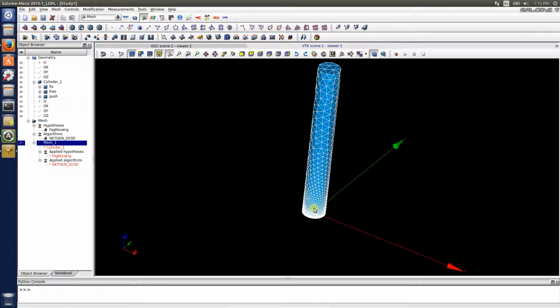And up there, as it's being pushed out, it widens out. So what you'll see is like a shape that's kind of like this. So it's not truly P over A. And you'll find your stress level is higher than what you expect. You know, you expect just P over A being the stress. It's not going to be that way, really.